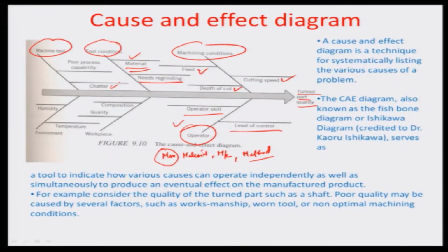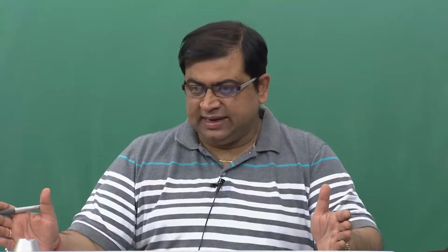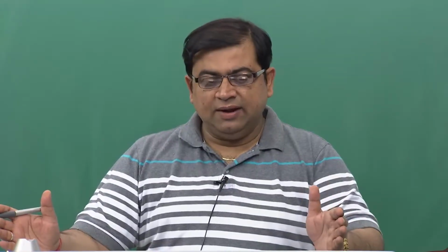We can also talk about whether the process capability of the system is poor, is it really producing a mean distribution of the outgoing quality which is deviated from the specification mean, or maybe is the process an outlier completely from the specification which has been given, or is the machine really ready to support the specification. Can it have a sigma which is tight enough, can it have a deviation which is tight enough so that it can lie within the specification.